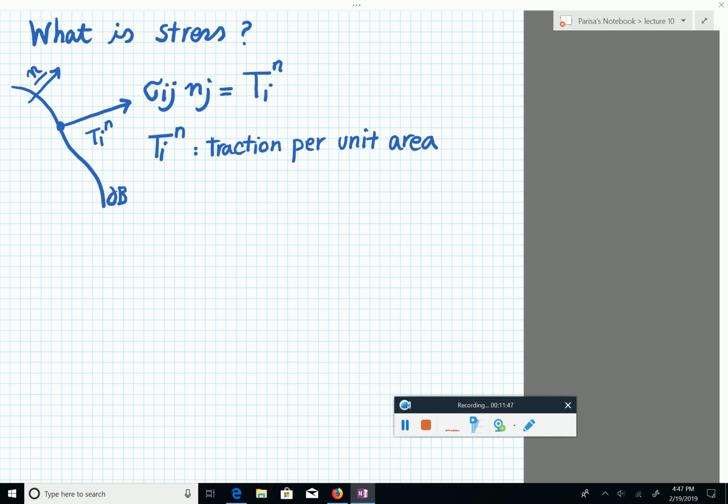Vectors. Forces are vectors, no problem. And this is force per unit area. So now if someone asks you in a cocktail party, what type of object is a stress? You say it's a tensor, and that person says, no, it's force per unit area. You say, no way. Actually, it's a mapping. It's mapping what to what? Can you tell me? Take 30 seconds. Talk to each other. It's fine. So it's mapping what to what?